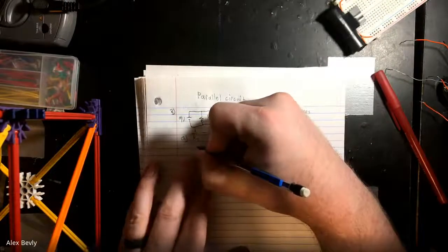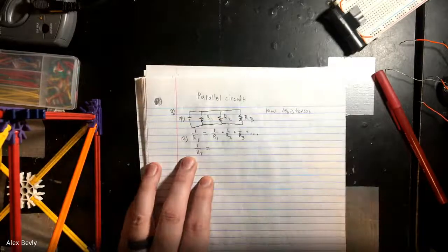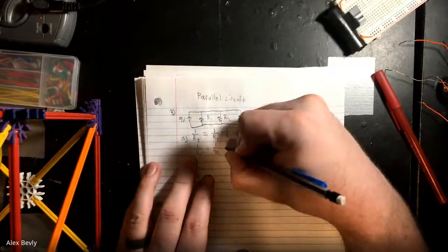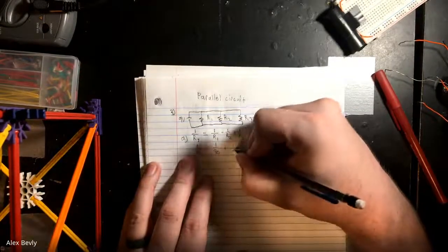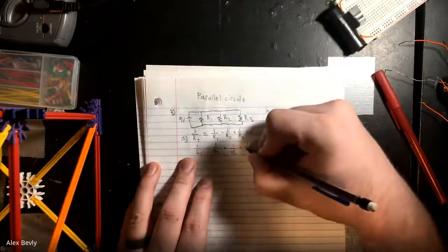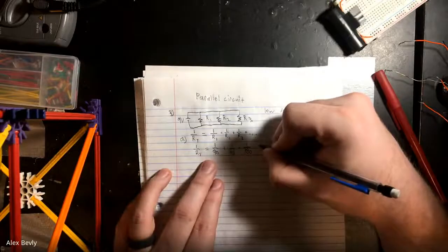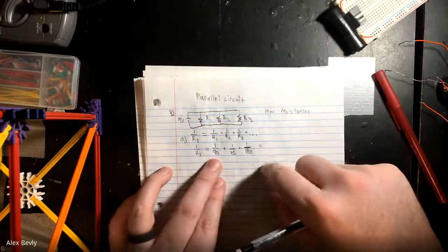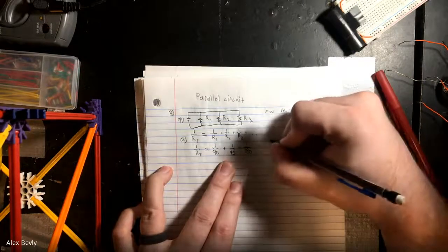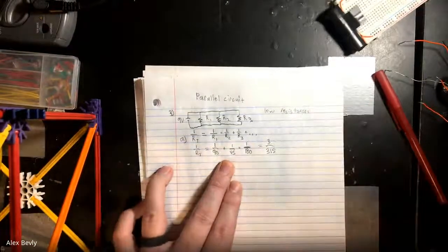So this equation is going to be easy to mess up for a few reasons. 1 over total resistance. Well, resistor 1 is 90 ohms, so 1 over 90 plus 1 over resistor 2, which is 45 ohms, plus 1 over resistor 3, which is 180 ohms. Now, when I add these all up, this is obviously 1 over 180 plus 1 over 90 is 1 over 270. Well, 2 over 270. And I can just add up the tops. This is just 3 over 270 plus 45 is 315, right? This is 3 over 315, correct?